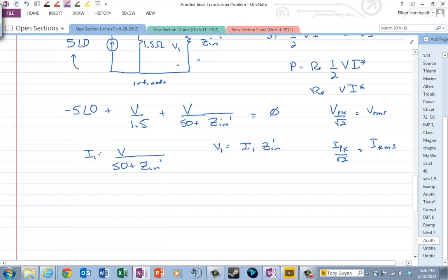But I generally think we're sort of used to using those formulas in the early chapters, like V squared over R or I squared R. And remember, that's really requiring us to be in RMS values, because if we looked at DC sources, the RMS value is the same as the DC value, and so that's how they're related to each other.